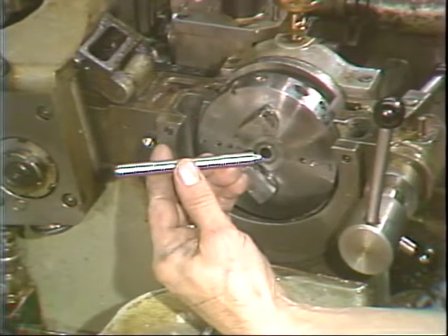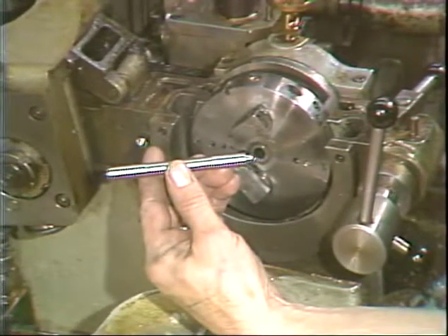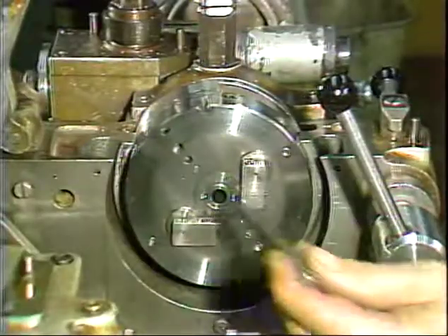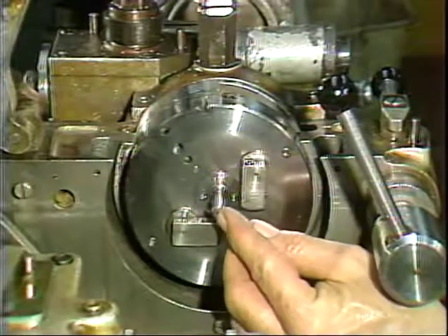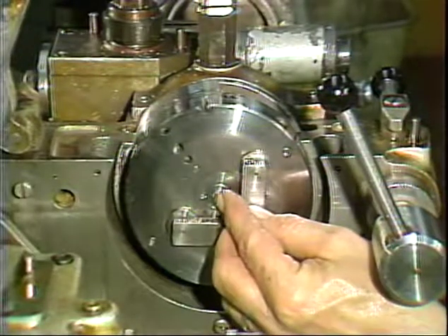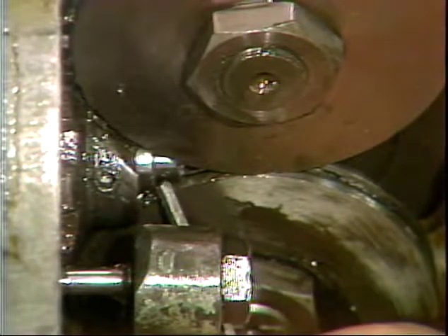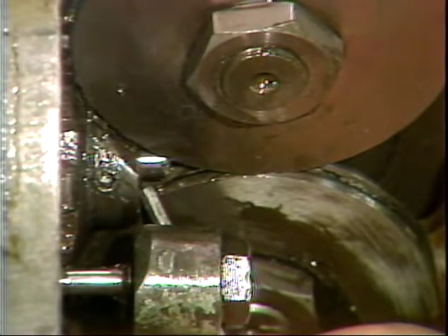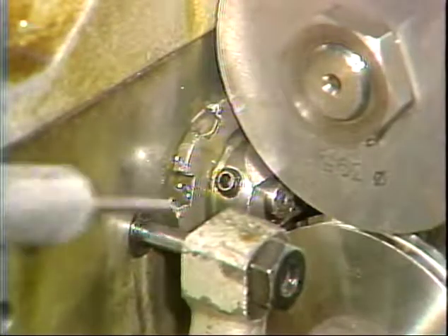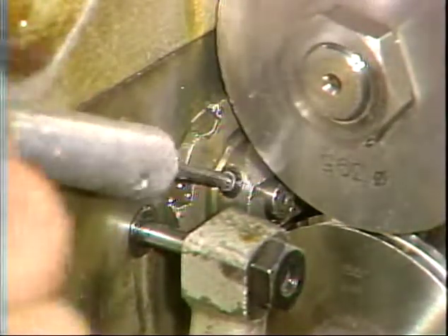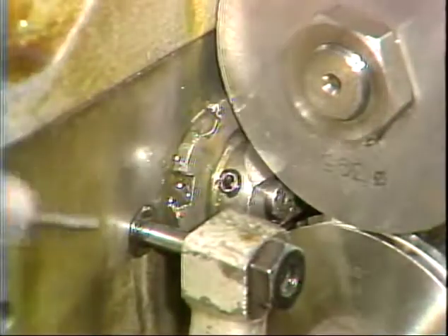Before installing the bushing, wipe off and clean the bushing and its mounting area. Slide the bushing in and through the tool head. The back of the bushing should not interfere with the feed rolls when they are in the clamped position. Lock down the set screw. Any final bushing adjustments will be done in a later lesson.